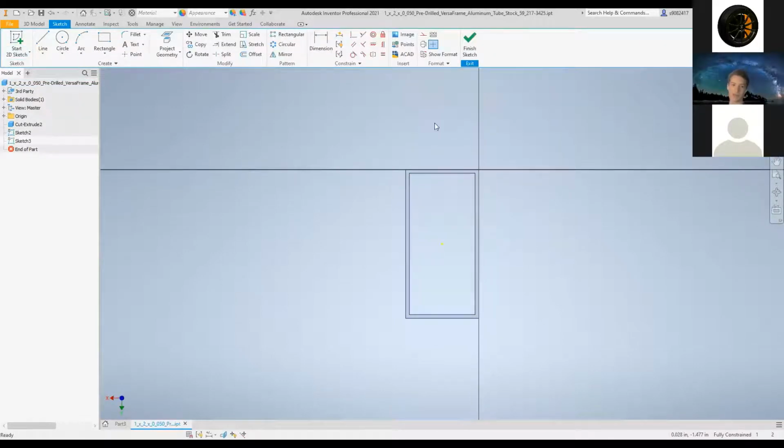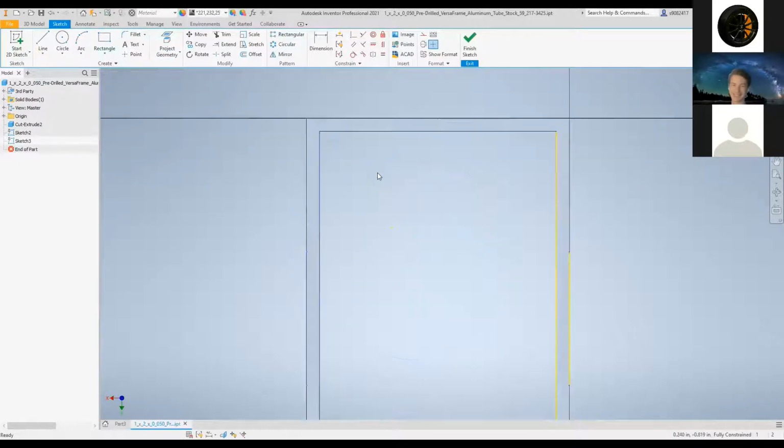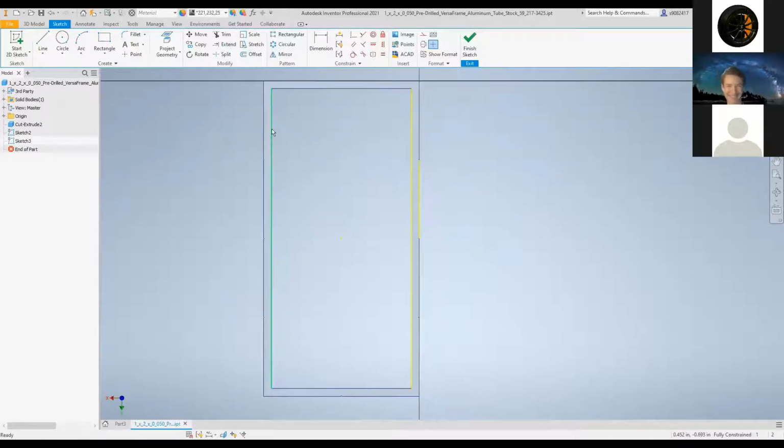You can do it a lot of ways, but if you want, you can just click project geometry to get the exact shape. You have to zoom in to click on the whole face. So project geometry just projects all the edges on the 3D object. If you click an edge, like right there, that's a click each. Can I just select all of them? If you zoom in and you go to the face, then yeah. Oh, no, you've got to click project geometry again.